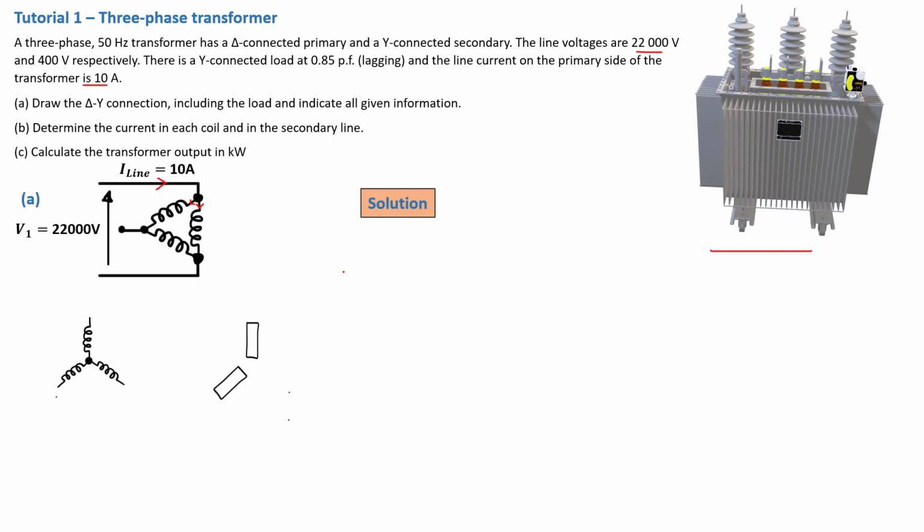So we've got a load also in a star fashion, and that is then connected to our transformer star windings, okay, in this fashion. And we've completed the connection of that line, and we complete another connection there. And then remember, the line to line voltage from our secondary side to the load is given with a value of 400 volt.